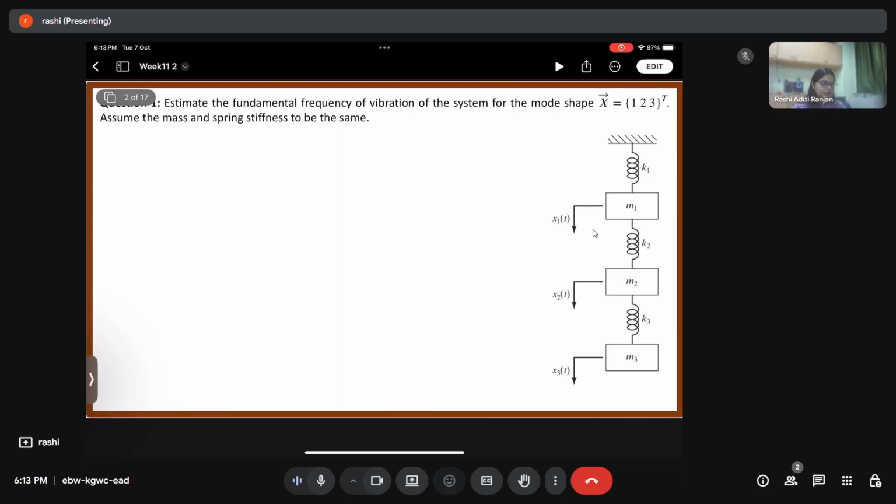They are related to each other, and we use those because if we have the mode shapes and the modal frequencies, we can write the general solution on the basis of those. Or, if we excite the system with that particular frequency, we can write how the solution is going to look, correct? Now, this is opposite to what we were doing in the previous case.